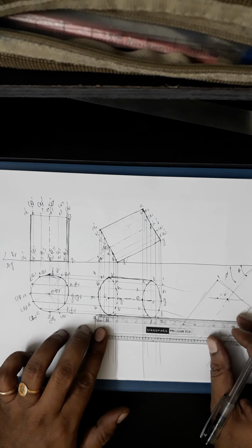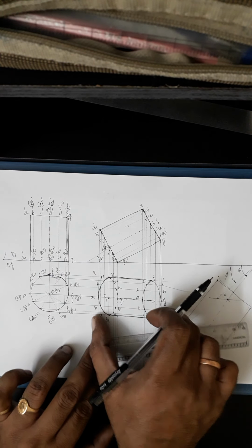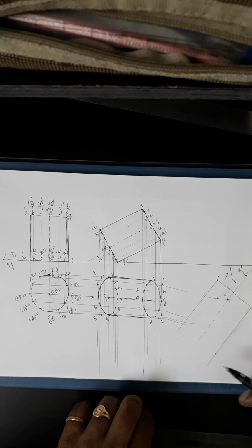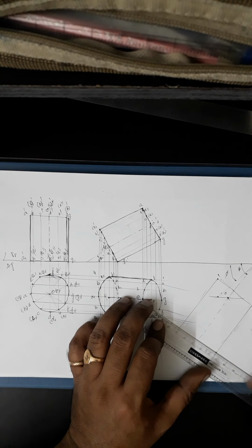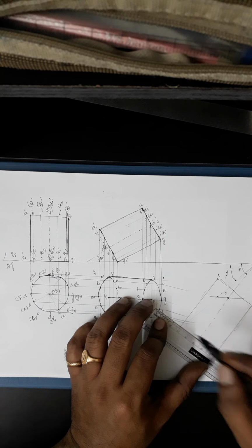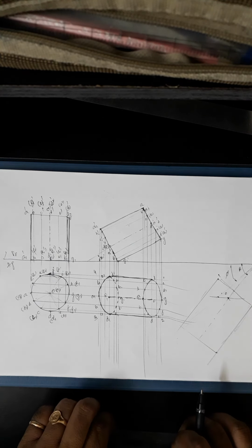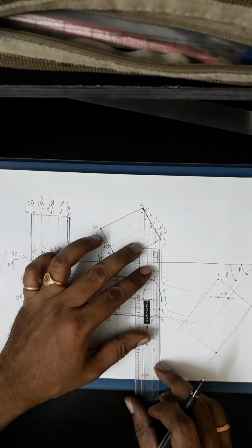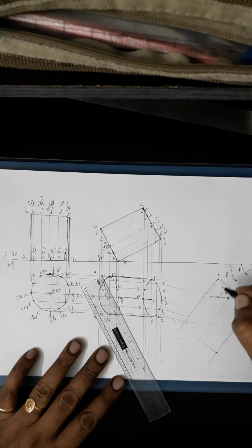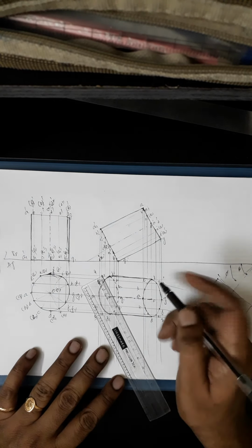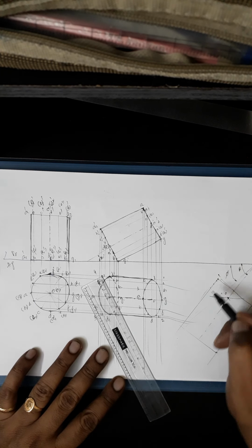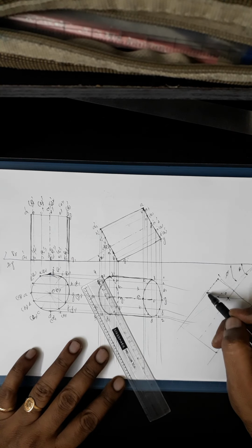On that I will take this distance. Don't measure anything. Take it with a compass or divider and just transfer, because you cannot measure that length, as it will be an unknown length, maybe in decimals of mm. So this is 3, 4. Then you have to construct the same grid now. Taking this length, go from here to here, mark that point, then here to here, get one more line, then transfer that length, and one more. That way you have to draw all the lines.